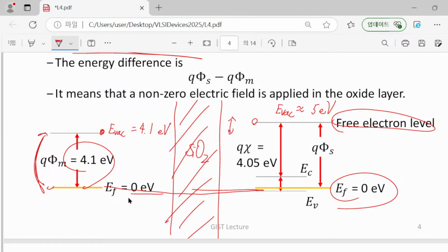Since the silicon dioxide layer is existing, from now on, that is really important, so let me state it slowly. Since we have a perfectly insulating layer called silicon dioxide, even in the case where our two Fermi levels are different, there is no current conduction at all.